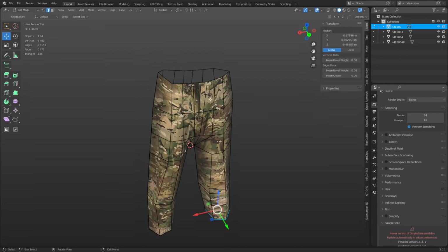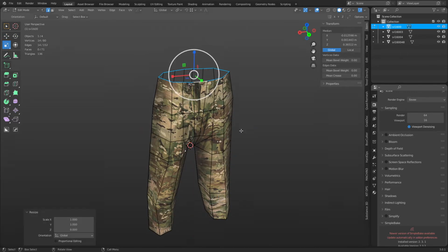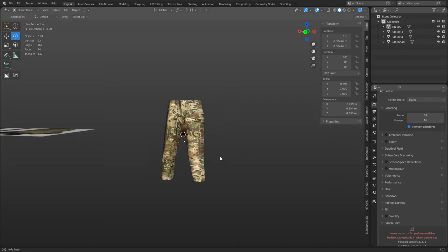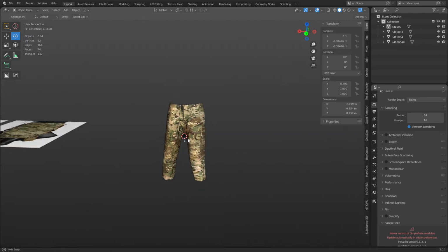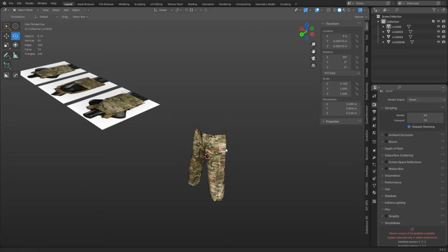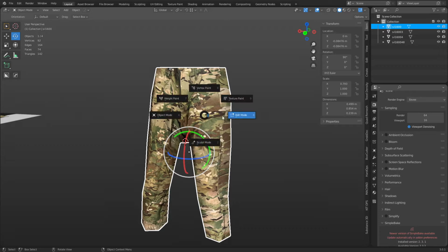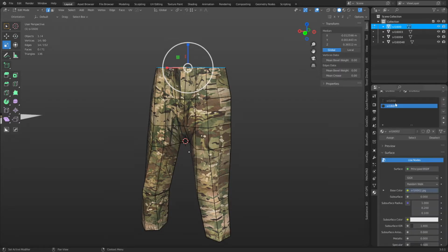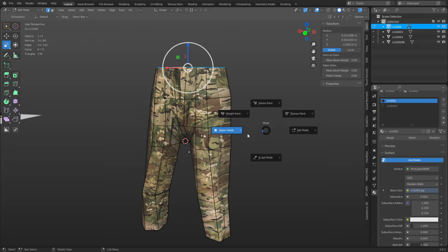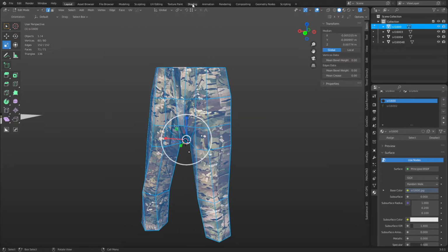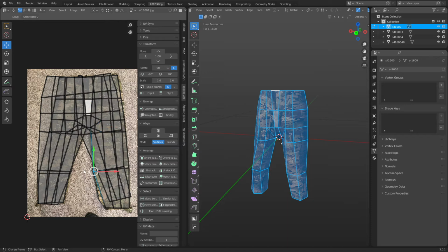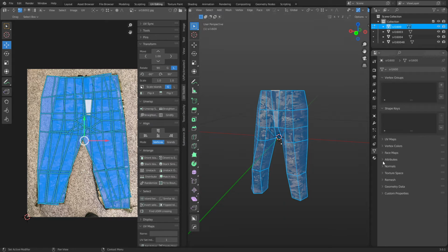Now, here's the caveat. As fun as all this is, because now we have character pants, no problem, right? If we cleaned it up even more, we'd have a good-looking face of a character here anyways. The trick is that this is two different materials, right? So if I go to the material panel, you see it's two different materials. At a certain point, they're already UV mapped like this, right? But we're going to have to create an atlas at some point. So you have to go to UV maps, click the plus sign, this creates a duplicate of this UV map, but now this one's here.